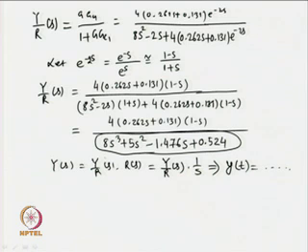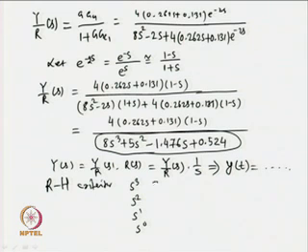If I look at the polynomial and make use of the Routh-Hurwitz criterion, with rows s cubed, s squared, s1, s0 and coefficients 8, minus 1.476, then 5, 0.524, the coefficient at this place will definitely be a negative value, and I do not mind what would be here.